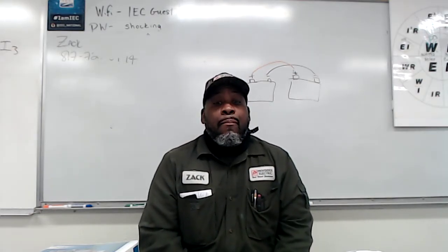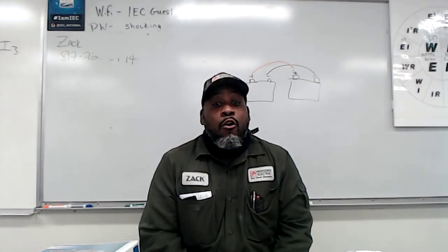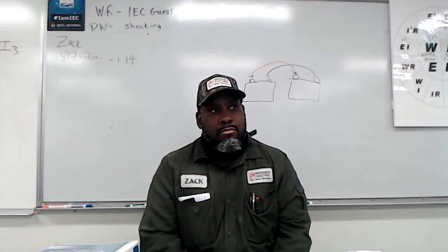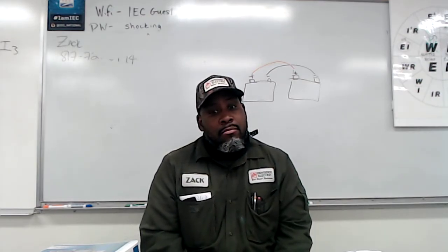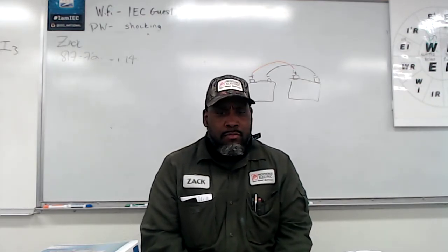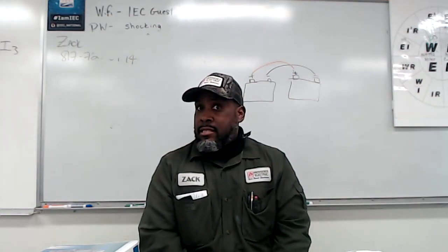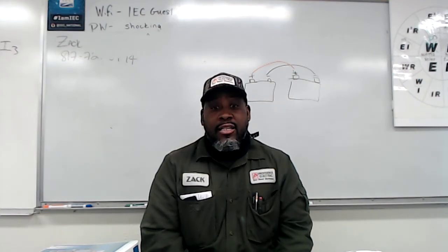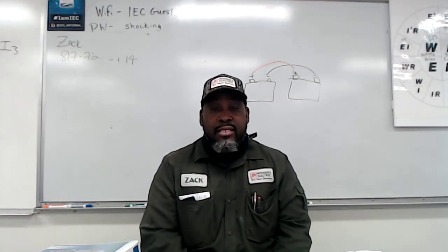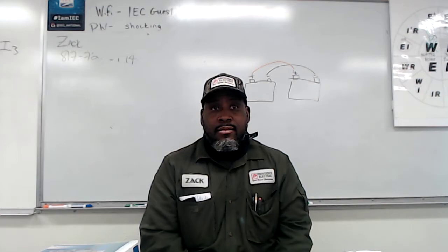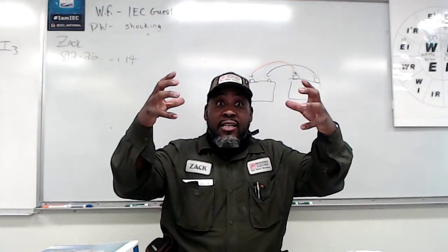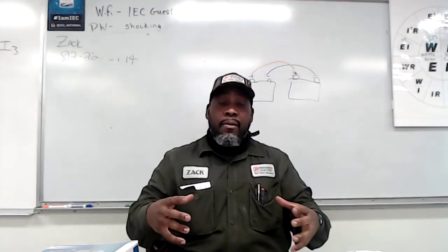So if I put all that together, do I get 24 volts? Yes or no? Yes. How? Because only 2 of the batteries are in series. Because I have 2 sets in series. I got the top set in series. I got the bottom set in series. But isn't that 2 batteries? No. I got 2 batteries in parallel on the top. I got 2 batteries in parallel on the bottom.